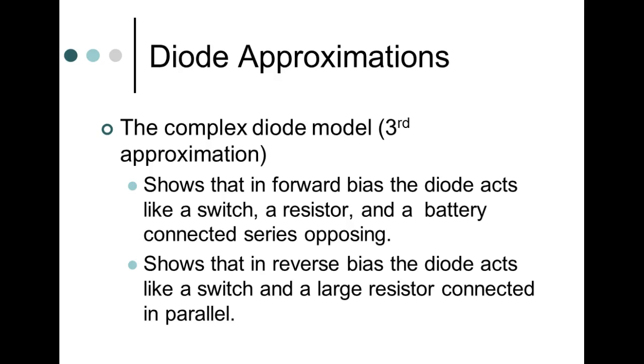Especially when you're dealing with resistors and capacitors, because the values on all of our components are approximations, right? You understand that? So if I've got a 1K ohm resistor in my hand, what's the likelihood of it measuring exactly 1K? It's probably more unlikely than likely, right? So every one of our devices has a tolerance.